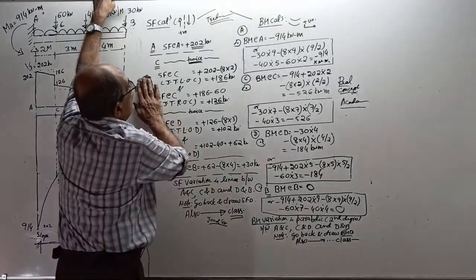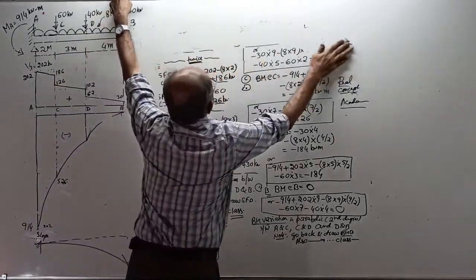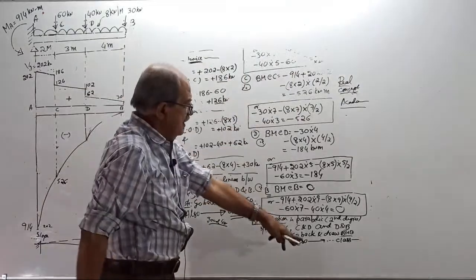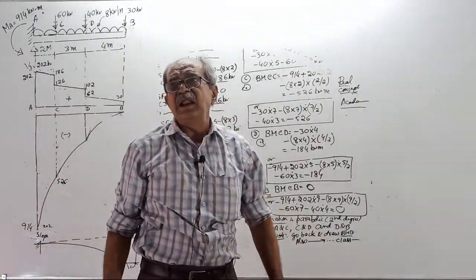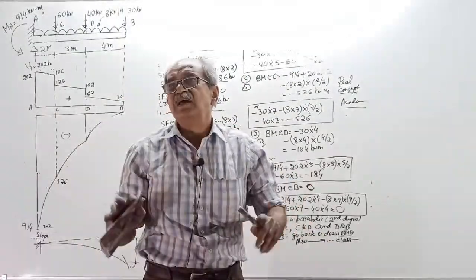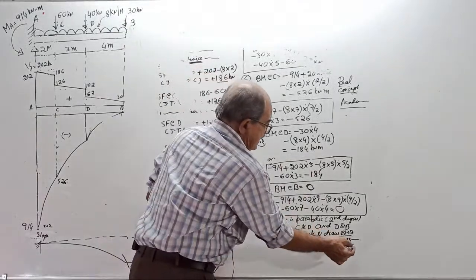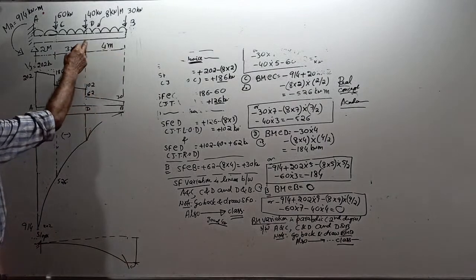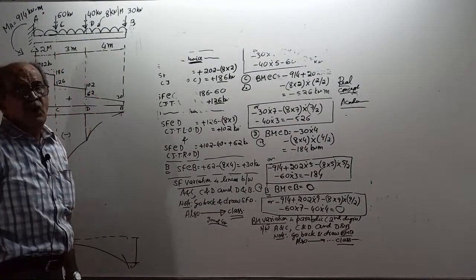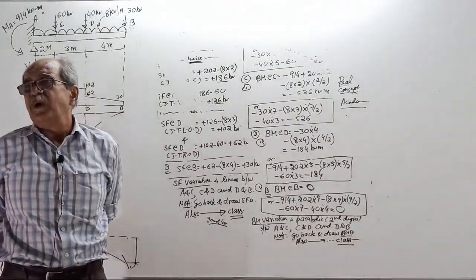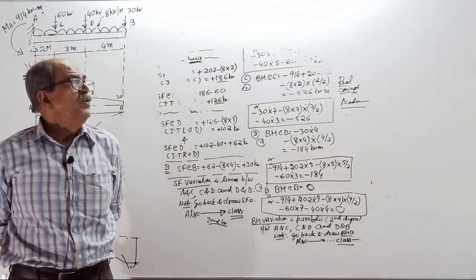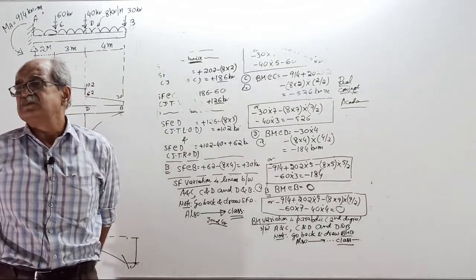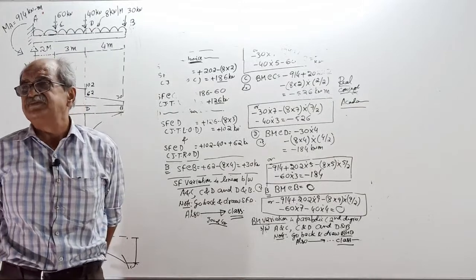Now, see, the traditional way is over. One more thing: the bending moment diagram is drawn. Oh, forgotten, see, some more statements you write. BMD drawn. Now, after finding the bending moment at all the standard points, you also find the bending moment at the point where the SFD crosses the baseline, or where the SF is 0.